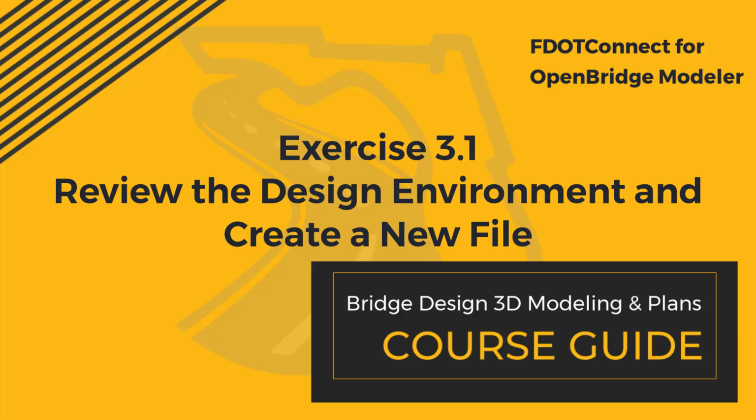In this video, we'll be covering exercise 3.1 from the Bridge Design 3D Modeling and Plans course guide. This exercise demonstrates reviewing the FDOT Connect workspace and creating a work set. Let's get started.